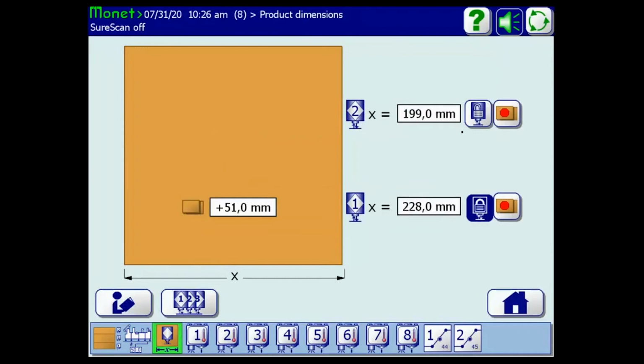All right, each trigger has 2 icons, a lock, we'll talk about the lock first, and an overlap icon. So the first thing we'll talk about is the lock icon. The trigger lock, I learned that you guys don't really need to use it, because you're able to position your trigger sensor on a solid portion of a panel where it doesn't have to fall into cutouts or holes or openings within the carton or within the product. So if your trigger is able to read a solid full length of the panel, that's most ideal, and that's what I would recommend setting up as.